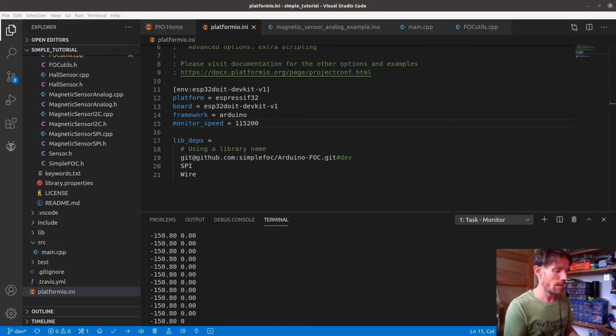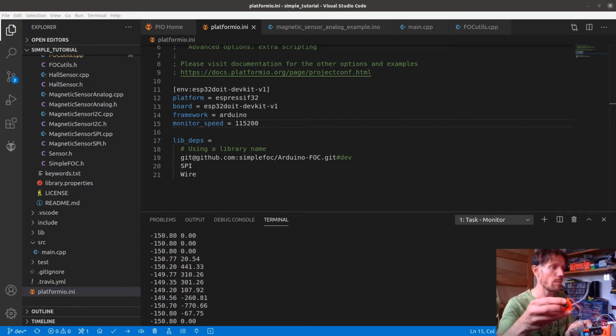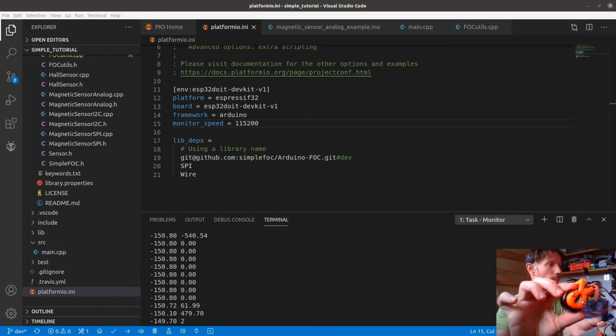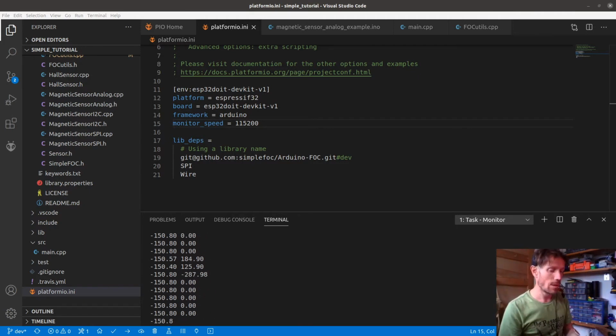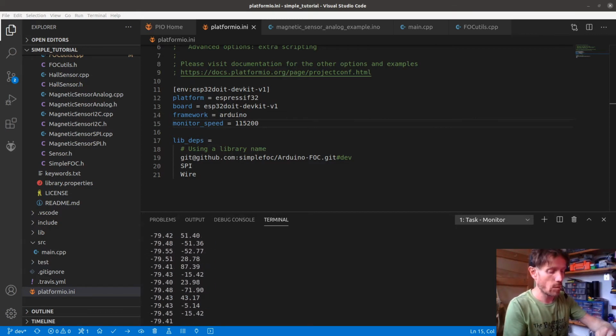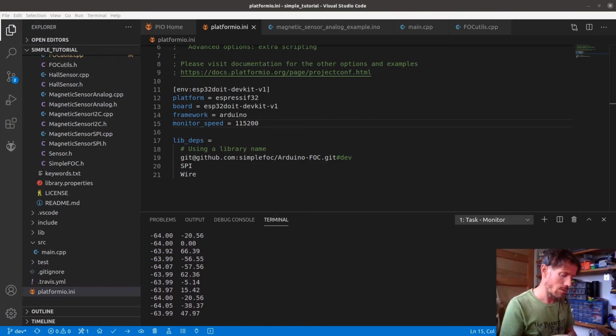So the gimbal motor, well, you can't see at the back of it there. You can't really see it, but there's an AS5600 in there, which is a magnetic sensor, and as the motor turns, the magnetic sensor goes from 0 to 1024. So 0 is 0 degrees and 1024 is like 360 degrees, and if you turn it a bit more it'll go back to 0 again. Right, has that fixed it? Are we back? Yeah, we're back. I think it's misbehaving slightly. Oh, the ground's fallen out again. I think me moving this is a bit of a disaster. Yeah, it's working. You can basically see me turn the gimbal and things happen.